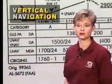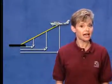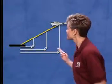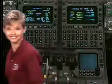Now, VNAV stands for vertical navigation. What that means is you have to have a navigation system that internally computes a glide path for you based on how far you are from the runway. Some fancy navigation systems you see in jets have this capability. It won't be long until we see this capability in piston airplanes.